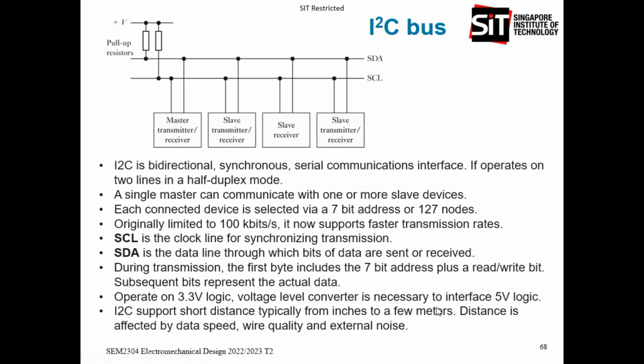For all these devices where you have a bus, why is it active low logic? It is because you do not know beforehand how many devices we are going to connect. Usually the output stage of all these buses is open collector, so you need to connect pull-up resistors.